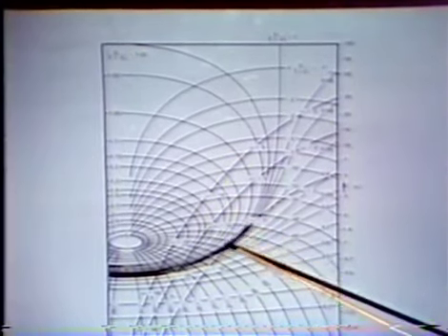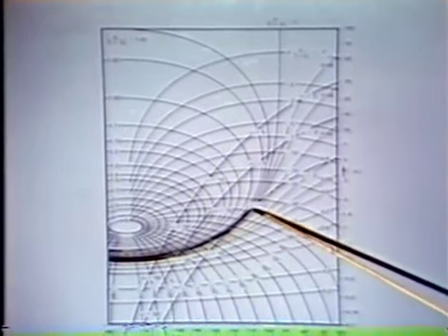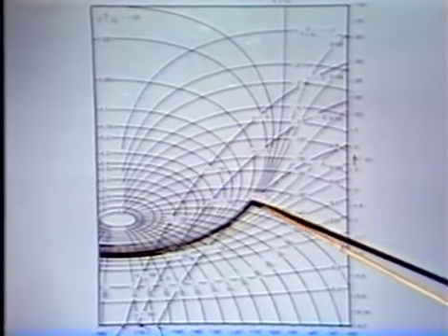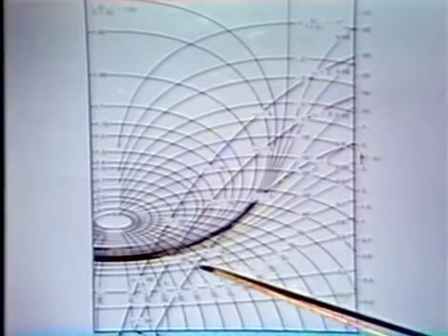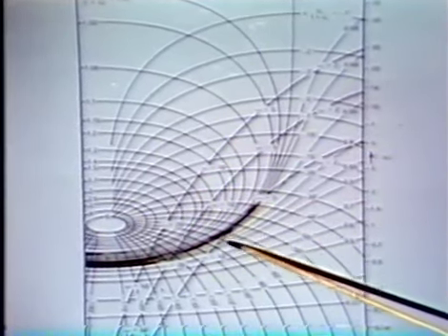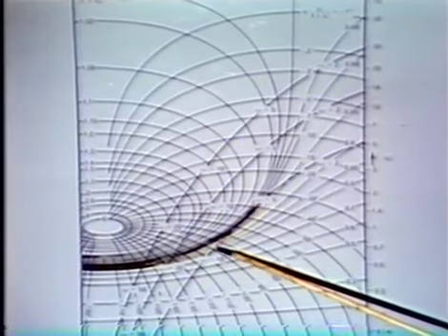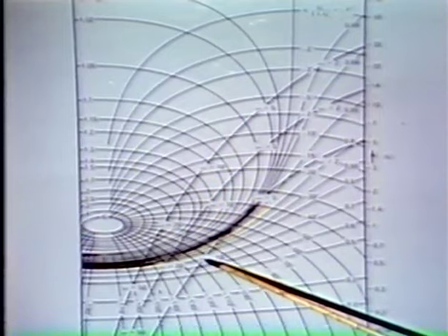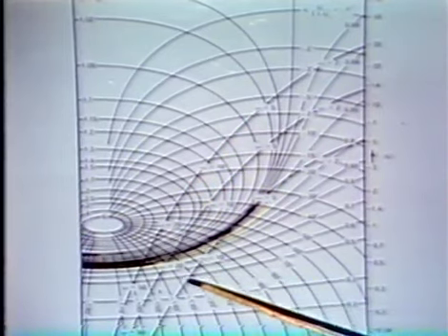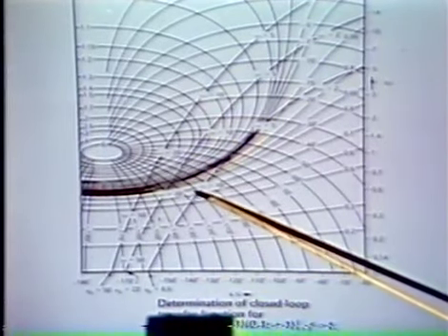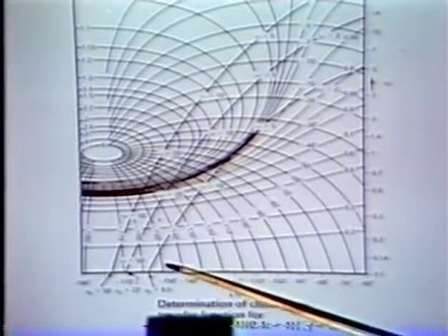The curve gets a little bit busy, but somewhere in here at omega equals 5, we hit a closed loop magnitude of about 1, and then begin to drop off to lower closed loop magnitudes. Here we're back down to 0.85, for example, and eventually we get to a magnitude of about 0.7 at omega equals 10. And if we keep track of things beyond that, the closed loop magnitude drops off roughly as 1 over frequency squared.